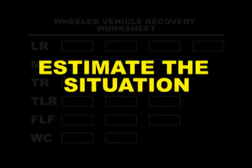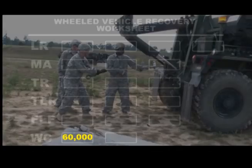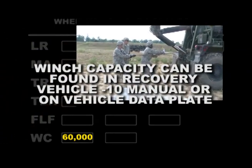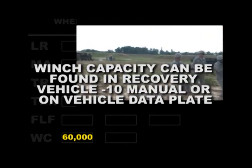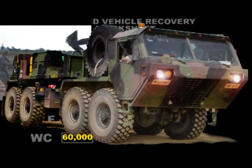Step 2 is estimate the situation. We will use the recovery worksheet to calculate the required configuration for recovery. We must first determine the available effort, which is the winch capacity of our recovery vehicle. The winch capacity can be located in the recovery vehicle's -10 manual or on the data plate. The winch capacity of our HEMTT wrecker is 60,000 pounds.